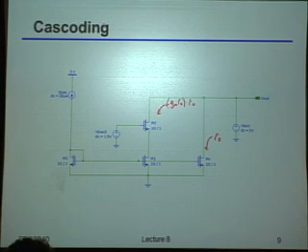Okay, so the second piece of what you said is really the critical part of it. Just to make sure that everybody heard and for the camera, the real trick here is that what that cascode device is doing is it's actually trying to fix that Vx right there. It's trying to reduce the variations on that Vx. Because here's the whole trick, right?